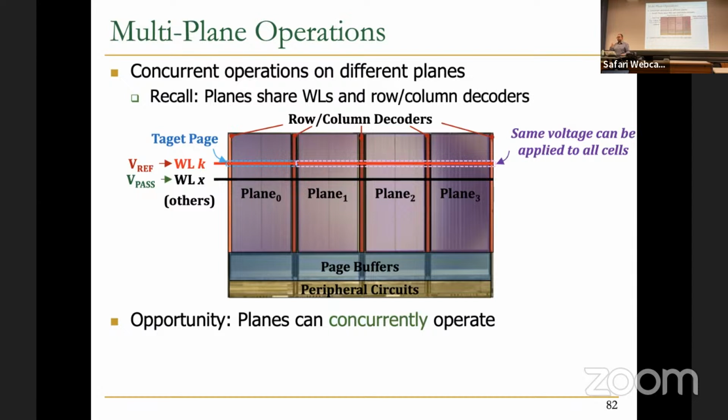So you have channel level parallelism, you also have die level parallelism, and you have plane level parallelism. If you want to get the maximum throughput, you need to benefit from all of it. And there might be some reverse engineering needed about the access pattern, like how the FTL maps things. With that, you can come up with the access pattern. There are papers for that, but Rakesh, do you have anything to add?